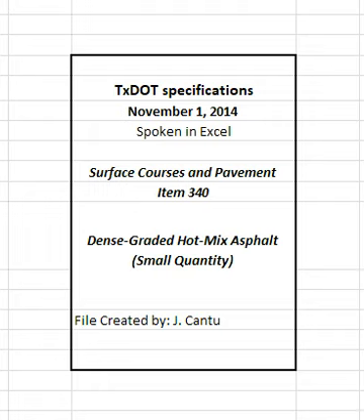Apply a thin, uniform tack coat to all contact surfaces of curbs, structures, and all joints. Allow adequate time for emulsion to break completely before placing any material. Prevent splattering of tack coat when placed adjacent to curb, gutter, and structures. Roll the tack coat with a pneumatic tire roller to remove streaks and other irregular patterns when directed.